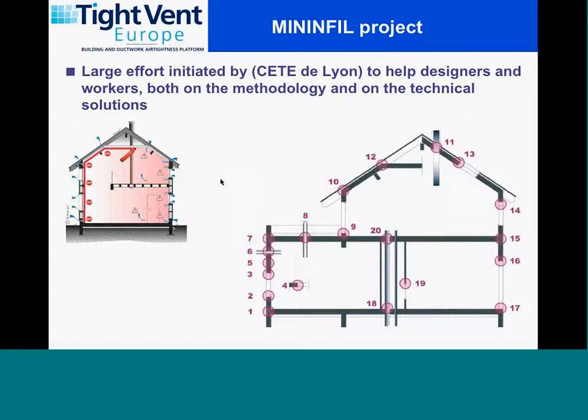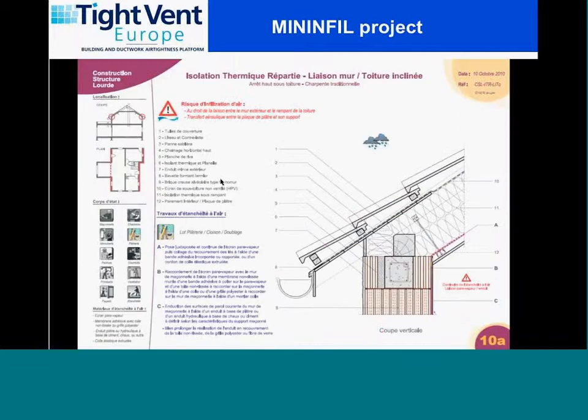These drawings are very nicely done to help designers and workers understand how you can actually make an airtight building. This is one slide of the handbook, where you can see that it goes very much into the details of the execution, because it tells you what kind of system you can use in order to build airtight at this connection, for instance, and also who is involved when actually installing this system.